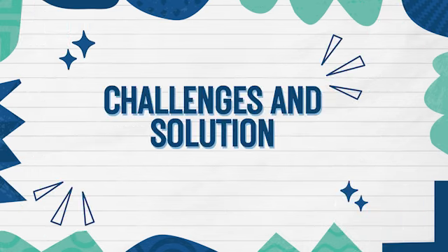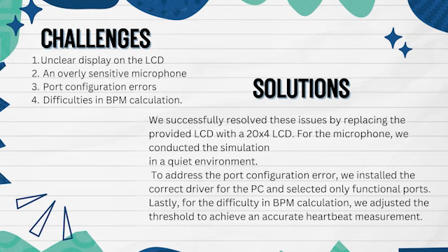Challenges and solutions. The challenges we faced while carrying out this project were an unclear display on the LCD, an overly sensitive microphone, port configuration errors, and difficulties in BPM calculation. We successfully resolved these issues by replacing the provided LCD with a 20 by 4 LCD. For the microphone, we conducted the simulation in a quiet environment. To address the port configuration error, we installed the correct driver for the PC and selected only functional ports. Lastly, for the difficulty in BPM calculation, we adjusted the threshold to achieve an accurate heartbeat measurement.